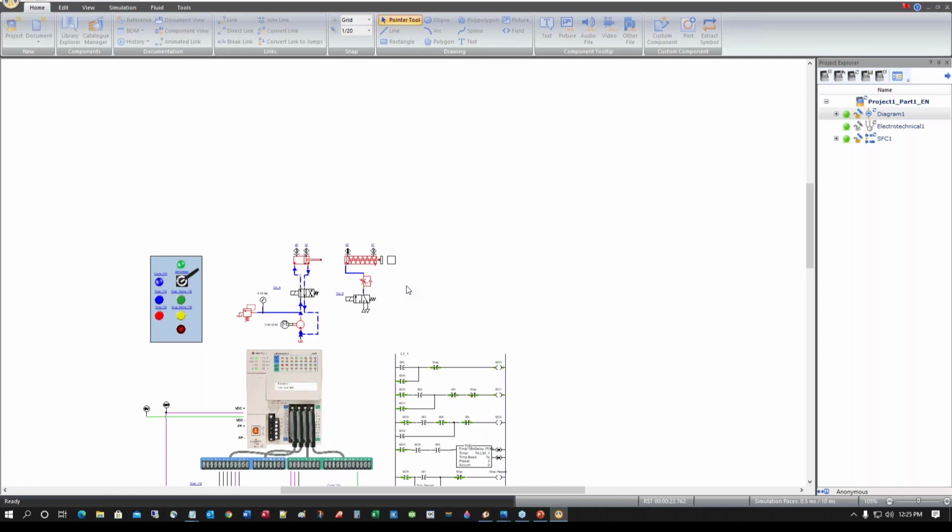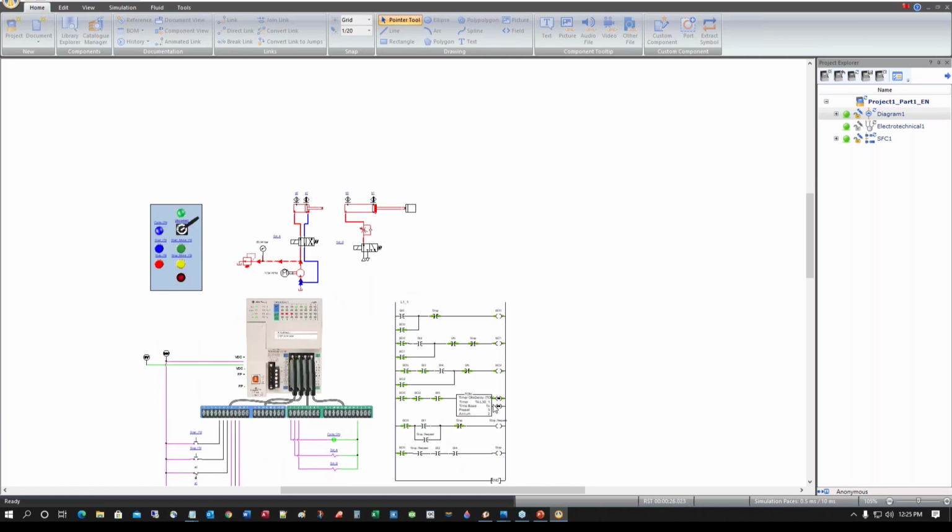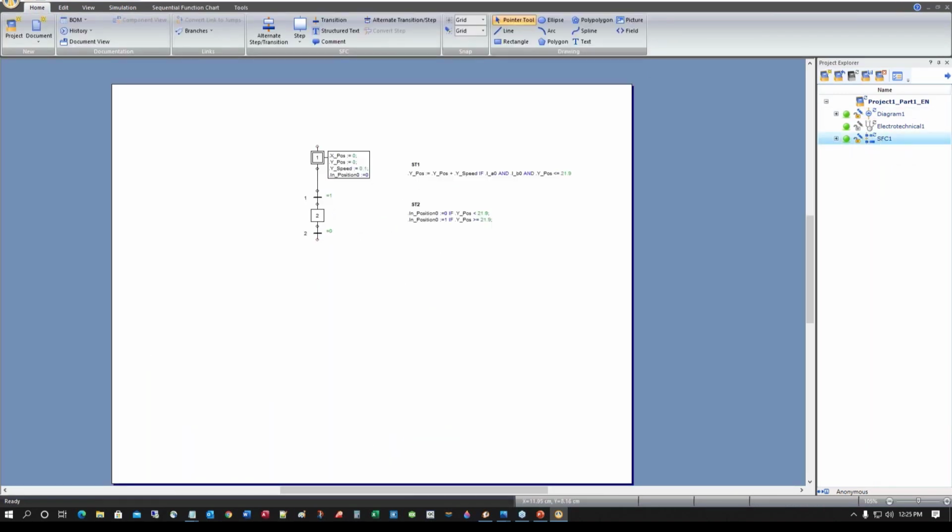Now I have to find a way that at the end of my cycle, I need this box to come back at the top and start trickling down over here. So I need a signal here to define for me the end of a cycle. Because at the end of the cycle, I need to initialize the x position to 0 and the y position to 0. So somehow I have to initialize them back again to 0. So if I go back to my graph set here, I need, reaching here at some point, to get a signal for end of cycle, so it comes back and initializes these things back to their initial position.